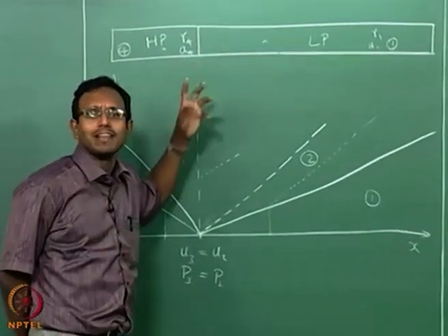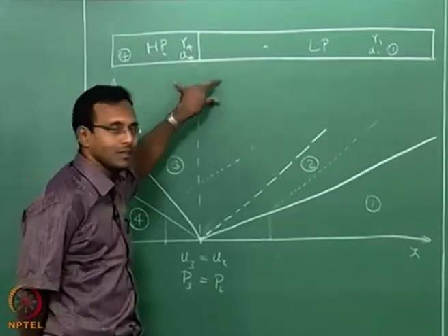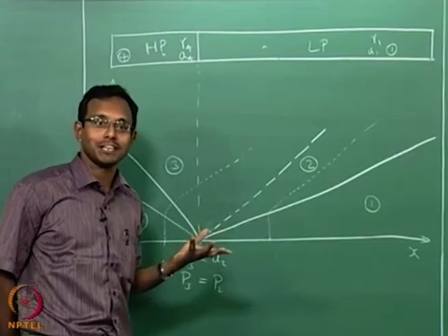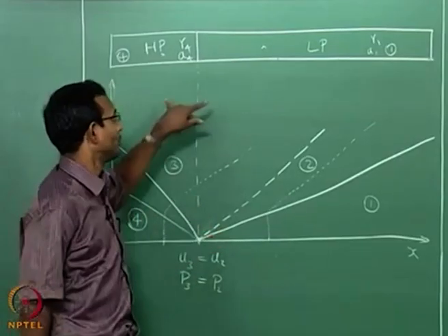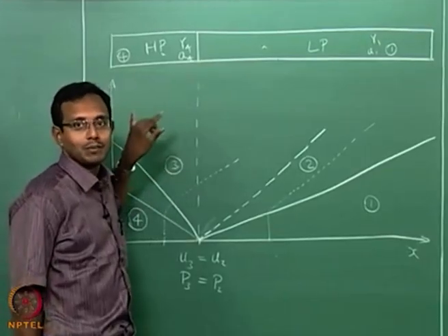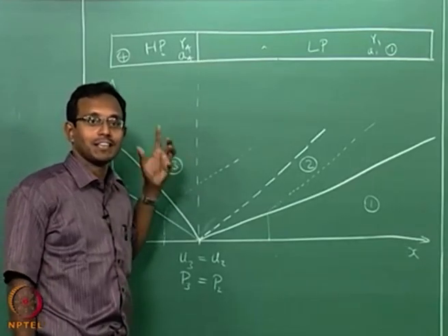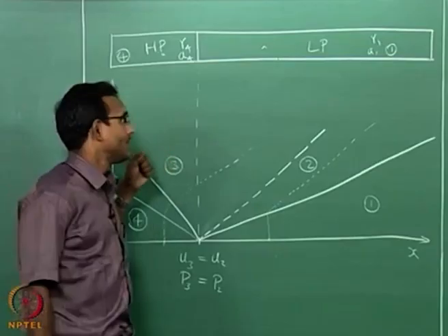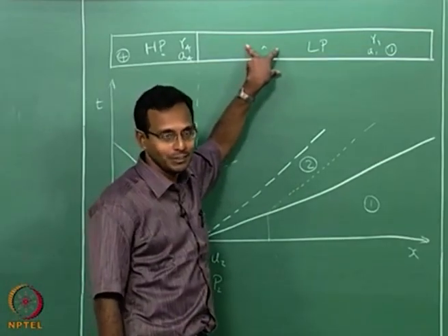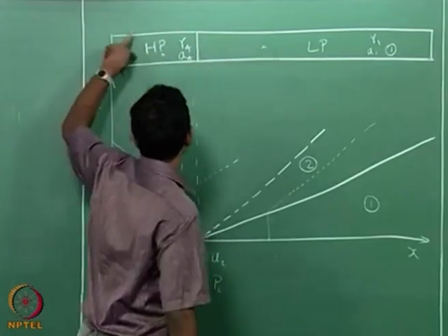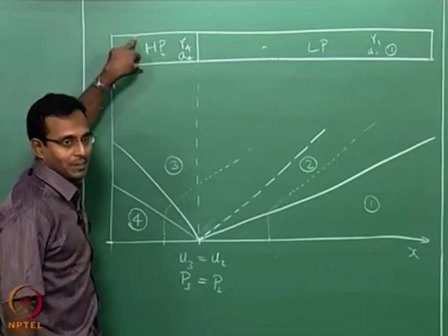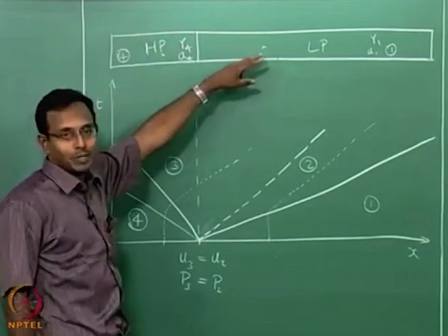Let us say typically the people who are using this will be chemistry people or combustion people, people who want to study reaction rates. Okay. Shock tube, if I just want to use the plain shock tube, it will be used by people who are in reaction rate determination kind of people. So they will have some reaction mixture which they want to study in here, and then probably very low molecular weight gas here, depending on what P2 and T2 they want.